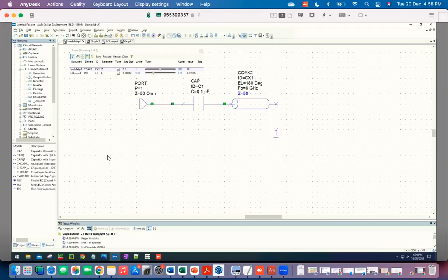So that's going to give you a reflection coefficient. And if that reflection coefficient is high, which means almost all of the power is being reflected back, then that's a weakly transmitting mirror, which basically just means the transmission coefficient is small, and vice versa. So the smaller the transmission coefficient, the stronger is the reflection and confinement, which means less dissipation, because the energy which is actually going to be dissipated is the part which is transmitted, right? So small capacitance, high impedance, more reflection, less dissipation, and hence high Q.